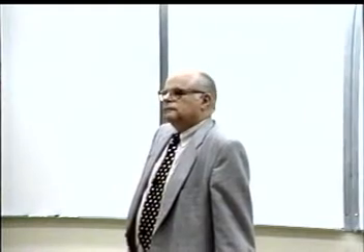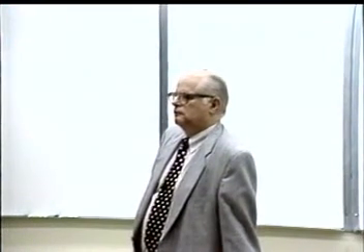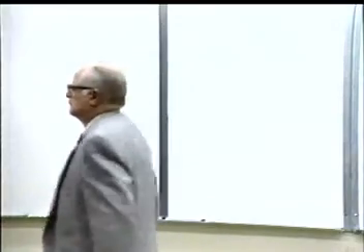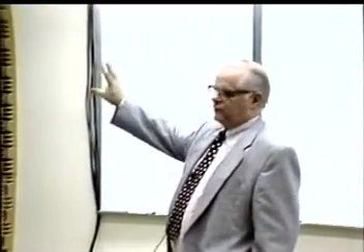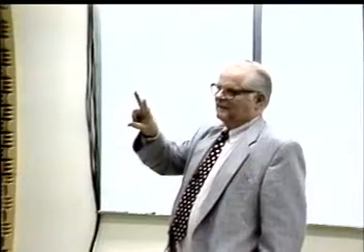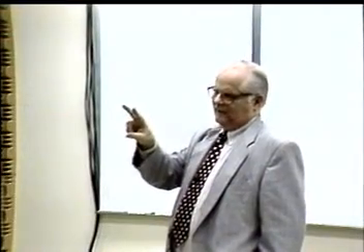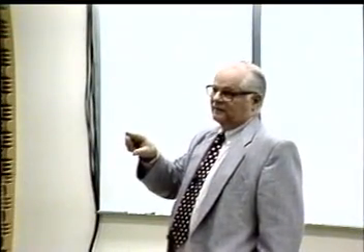What is the difference between application of your methods with simultaneous buckling modes and without simultaneous buckling modes, numerically? Well, we do not have enough information yet to make a categoric statement. It is definitely so, as I have shown you on the examples, whenever there are 2 of them present, you get a bigger decrease.